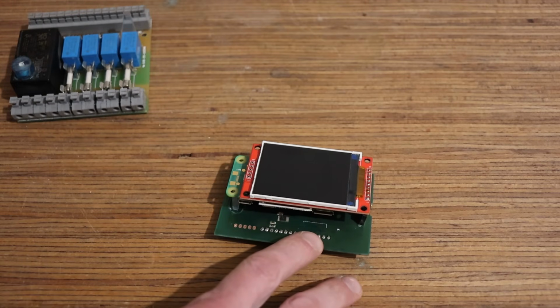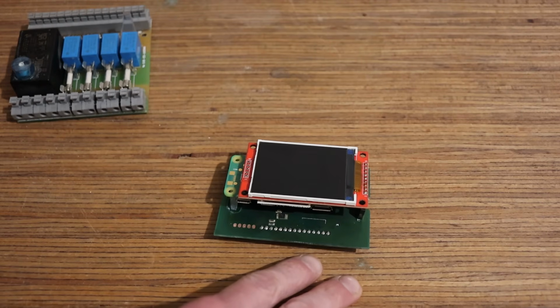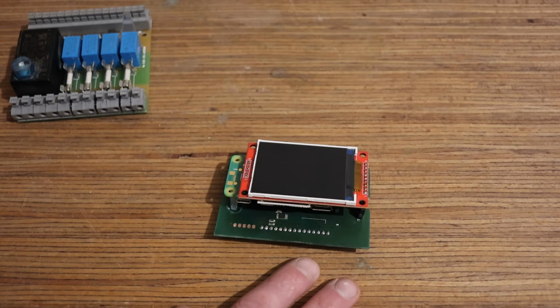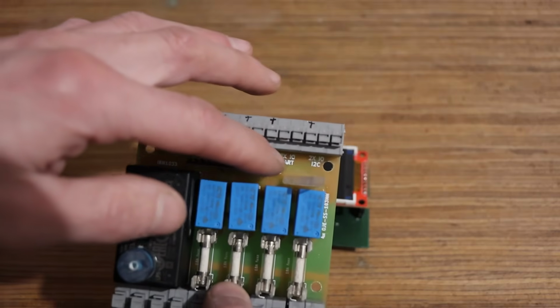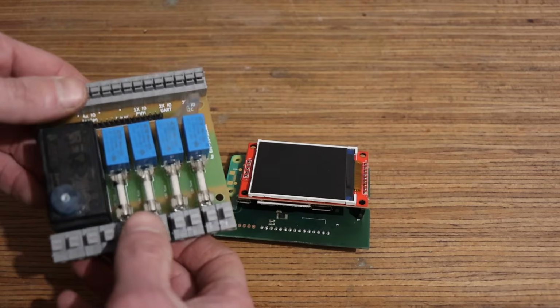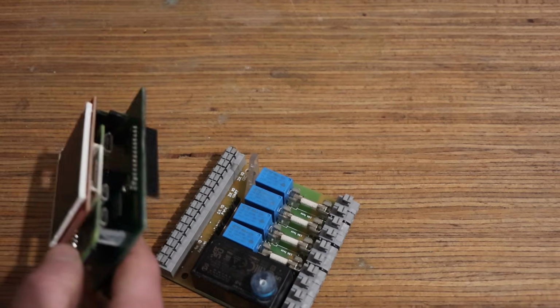I am expecting analog inputs to be very questionable, and I mean, these are questionable even with the Arduino thing. There is a lot of noise, especially if the main pump that pumps the water from the well to the house is running, because it is behind a VFD, so that is generating a lot of noise. Then obviously some mounting holes, something different than random offcuts of polycarbonate that I have found. This I have 3D printed with the intention of screwing this in.